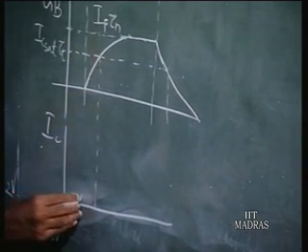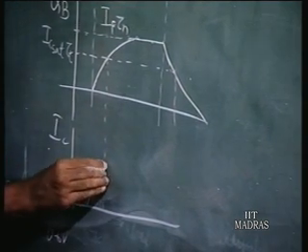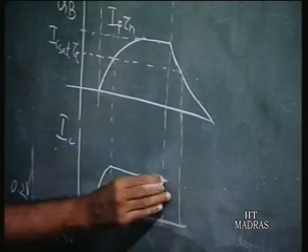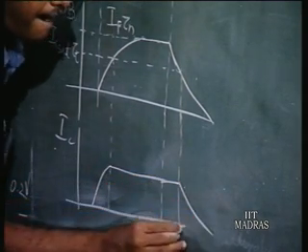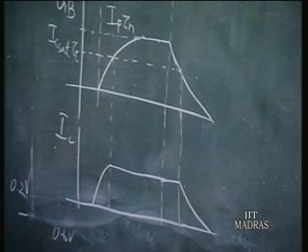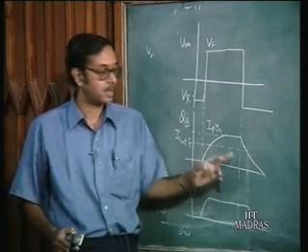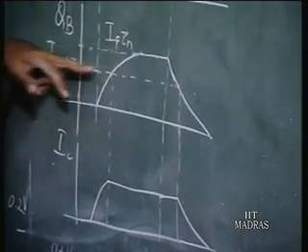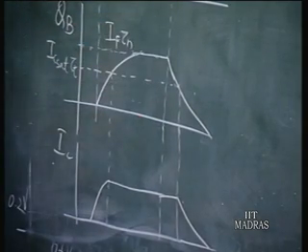The transistor goes to saturation, and it is going to remain in saturation, even here it remains in saturation, the current has not fallen, and then it is going to fall. Is it clear? Because only after this it is going to fall. This is the charge at saturation. So once the charge comes down to that, then only it is going to decay.